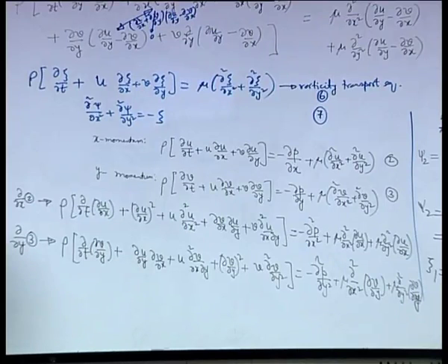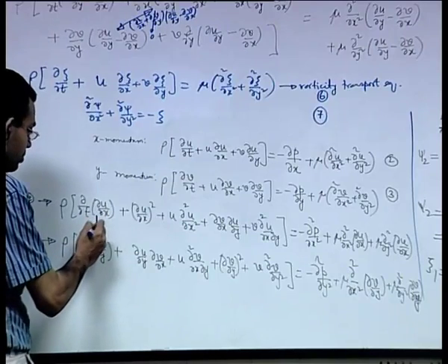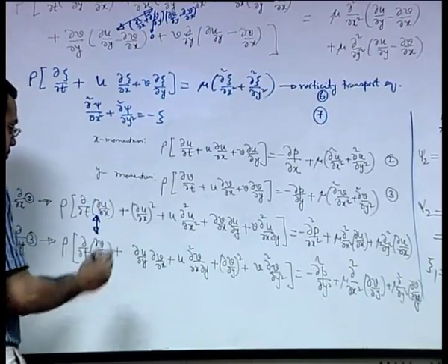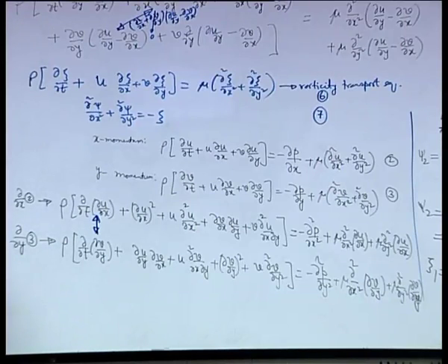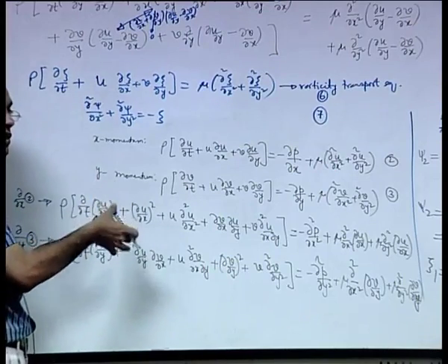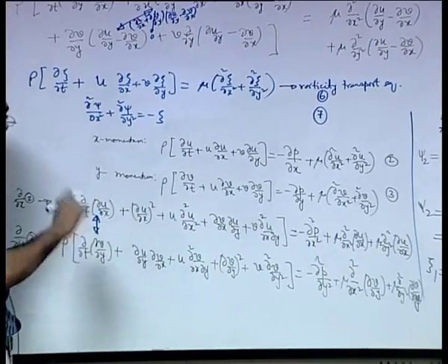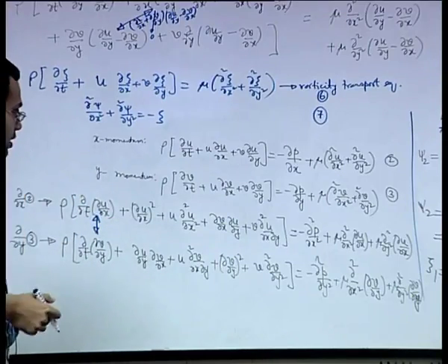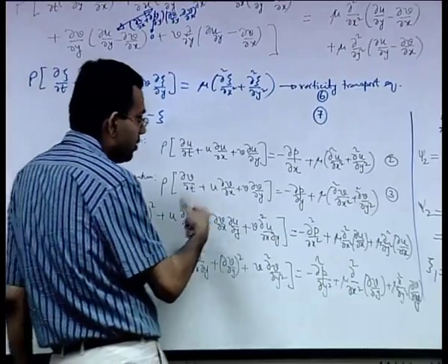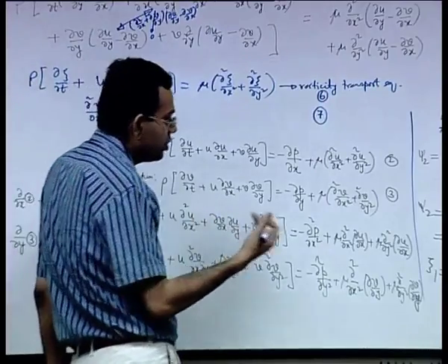Then what we can do, we can add these two. So, if you add these two, this will be del t of del u del x plus del v del y, by continuity that will be 0. So, the unsteady term is gone. So, one of the objectives that this manipulation satisfies is that the unsteady term is eliminated. Then the remaining terms are there, you can simplify it or you may not also simplify it.